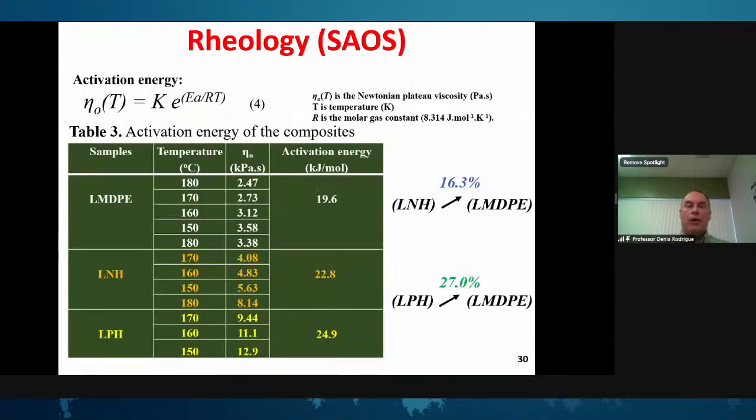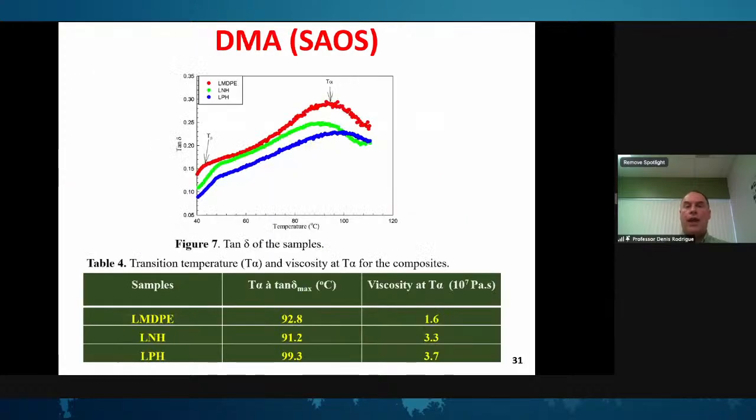Another thing that we are looking for is the activation energy. So all the properties are changing with temperature. We saw in this case that, again, due to the better coupling, the activation energy was much higher with the treated fiber. So again, this proves that you have some good modification at the interface. I will go fast on the other results because they're all giving the same information.